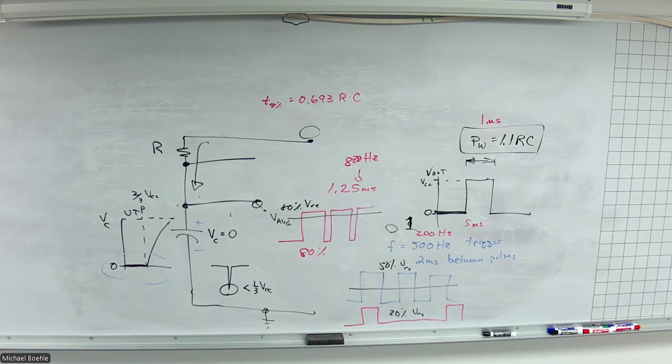The 555 timer, remember the output was what? It was a flip-flop, right? Not Q came out of a flip-flop. Very high speed response. This allows very neat, nice looking square waves up to fairly high frequency. But still, with RC, you're not going to get much above 1 or 2 megahertz. I haven't tried too hard to see how high I can go with a 555, but yeah. Make sense? All right.